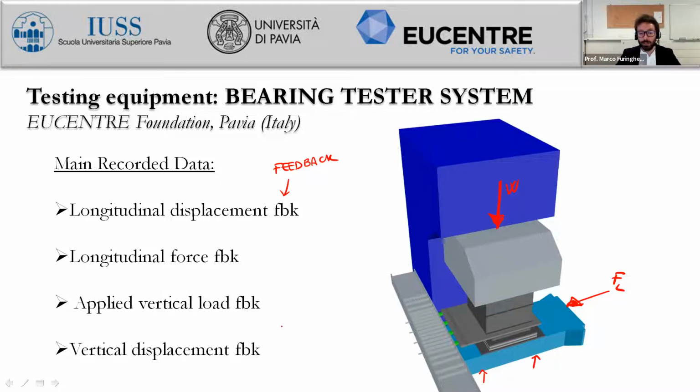And we are expected to find approximately no vertical deformation for rubber bearings because we are expecting to have planar behavior. For friction pendulum, for curved surface sliders, we are expecting to find the actual movement, pendular movement for the bearings. So we will try to understand and to measure the radius of curvature of the device by looking at the vertical deformation together with the horizontal one.